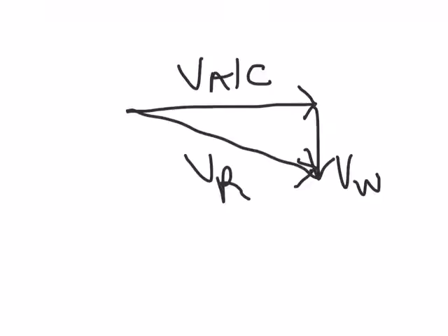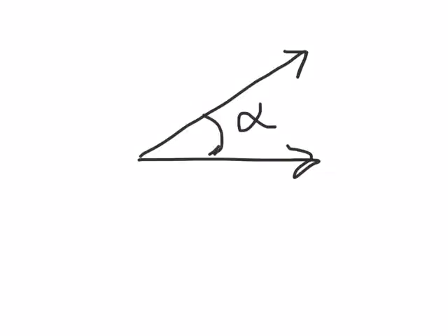So if an aircraft is in steady climb at constant airspeed and climb angle, the ground speed and the rate of climb can be found by this vector resolution. So very similar if we look at climb angle. So here's the horizontal component and the climb angle component, and this would be angle of attack.